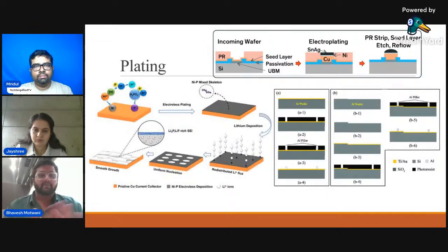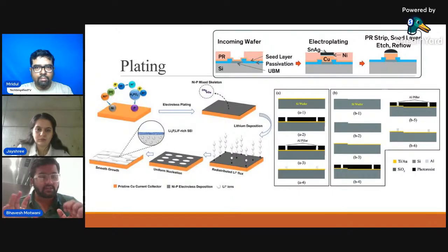Now plating, the best understanding for plating is to make some sort of a layer or bond pads to connect with another IC. Basically it is for wire bonding and for better connectivity. As we can understand, it can be a metallization part also. So it is generally done for the lead frame and ball grid array. You can see it on a QFN package, quad flat no-lead packages.